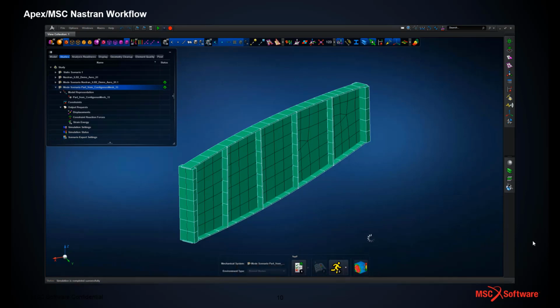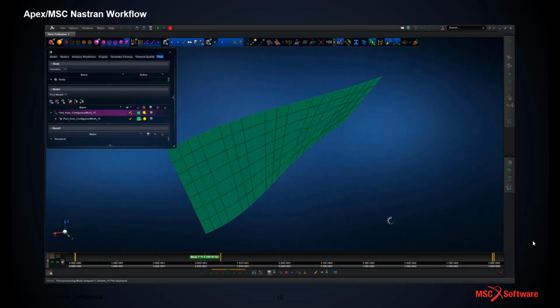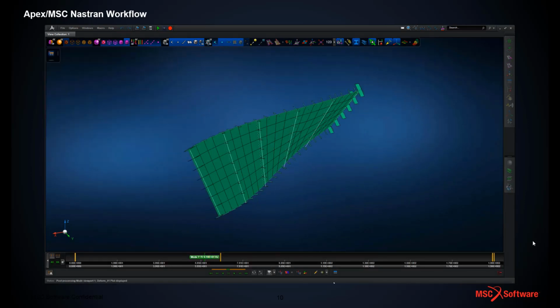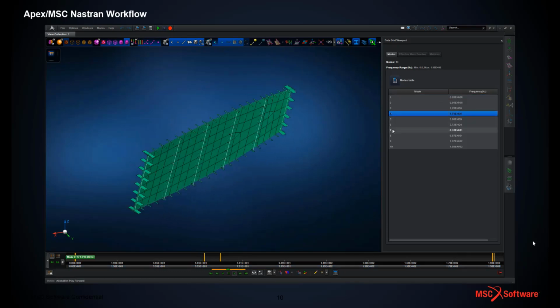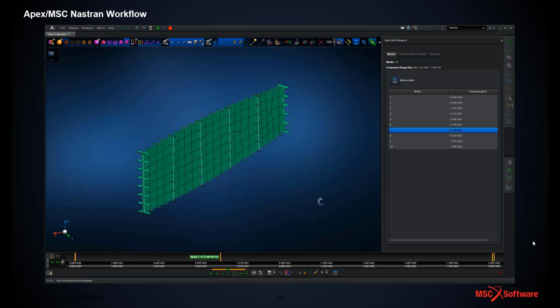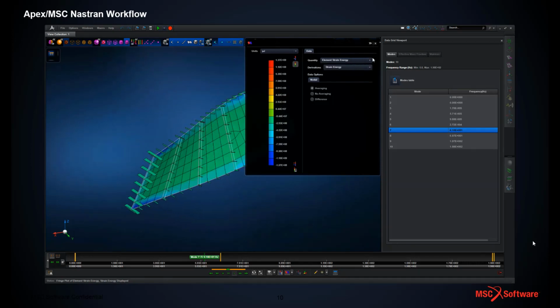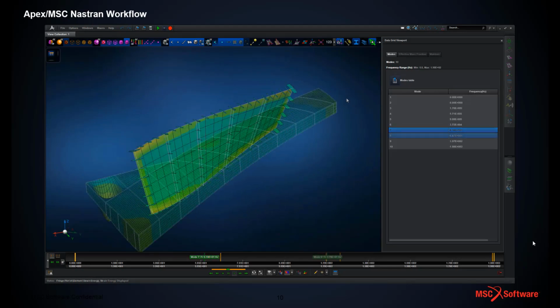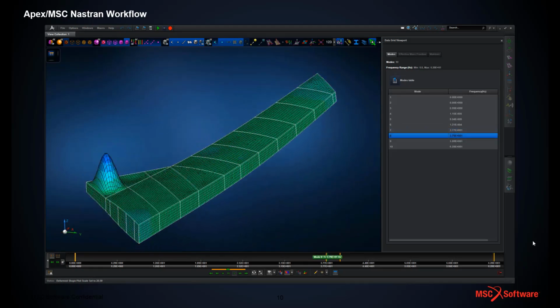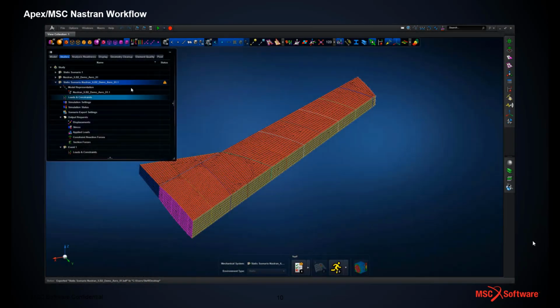Here we're just looking at a free normal modes analysis, just to understand the behavior and how things are tied together for this type of component within the full assembly. We can look at the mode shapes and the strain energy distribution. Modes 1 to 6 are rigid body modes, mode 7 plus are elastic body modes as per a standard verification type exercise, and we can look at the element strain energy, where that's peaking and what have you, just to make sure that the structure's behaving on a component level as we want. Then we can run that analysis for the full structure once we've got a good handle on how the discrete components are working.